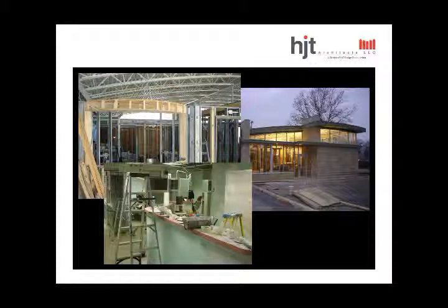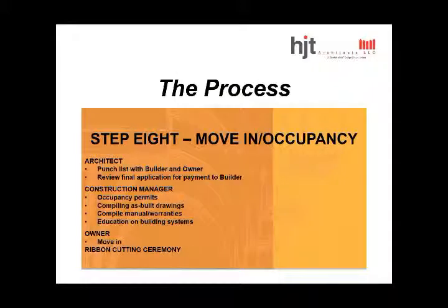Punch list is where you actually can go through, make sure every component is done to the quality of the drawings and specifications, review final applications for the payment to the builder, and then obviously the contractor or construction manager would get your occupancy permit, your as-built drawings, all the manuals and warranties, and educate you on your building systems, because there will be quite a few of those. And then lastly, the great move-in and the ribbon-cutting ceremony.